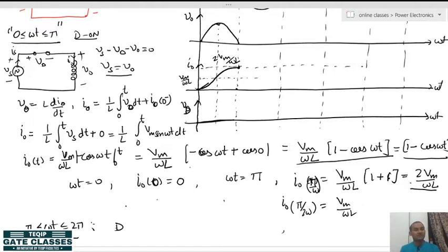Sometimes it happens, if you might have observed in your homes also, that if you repeatedly turn on and turn off a switch, it creates a spark there. Why is it so? Because of some inductance present there, due to wire or due to the motor load or any inductance, might be stray inductances. Because of that, when you do frequent switching at your home, the inductor current which is stored there does not allow the instantaneous change of current, but as soon as you try to break the circuit or make the circuit again, the current happens to change.